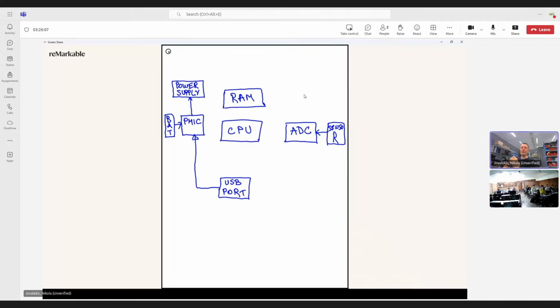There are also modules rated at different frequencies, not only 2.4, and they do not use any kind of protocol. They are simple. So basically, you define your own protocol. You have just a physical layer. You have just a transceiver. So it is able to modulate, send, receive, and demodulate. That's all. And there are a bunch of these chips. So we will call it just RF transceiver. We'll put it here. The data rate this needs to go is 250 kilobits per second.